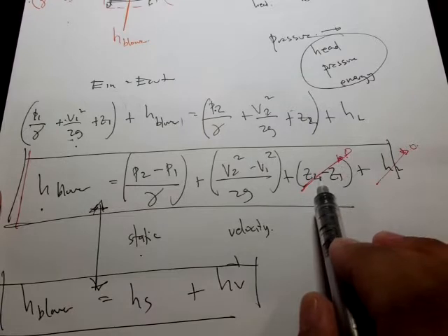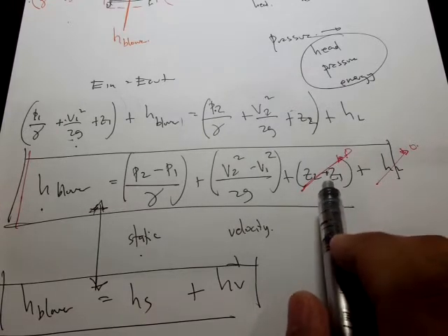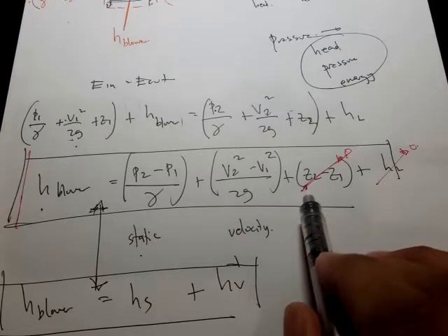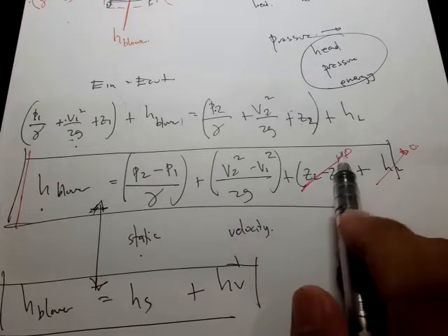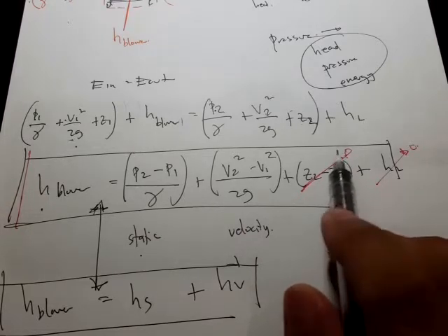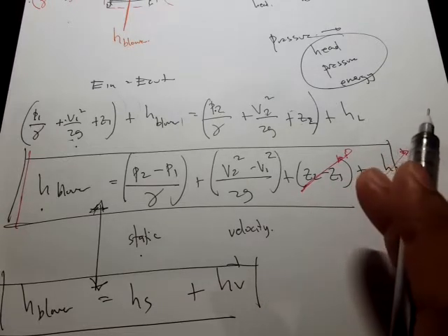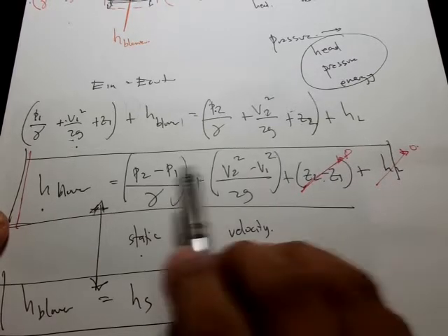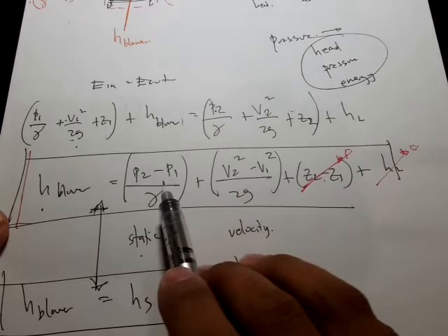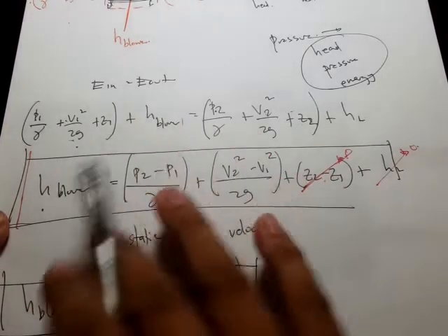So again, this is only true if the elevation is negligible, if our fluid is air or a gas or a fluid with a low density. But in pump systems, later on, we'll see that we include this, but this one gets to be the zero term depending upon the system.